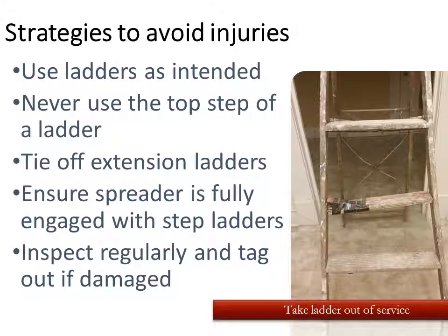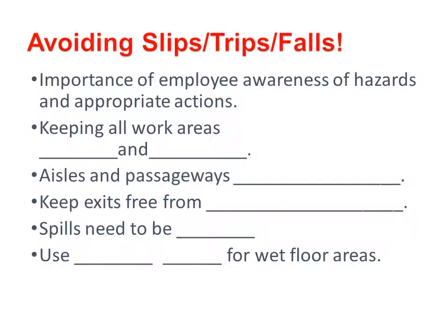Use ladders as they're intended, so vertical ladders should not be used as horizontal platforms. You tie off or lash down your extension ladders. Ensure that when you open up an A-frame ladder, the spreader is fully engaged, and inspect regularly and take out of service if they're broken.